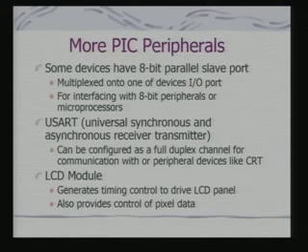There are other PIC peripherals besides what we have discussed so far. One is the 8-bit parallel slave port. If you look at your digital I/O pins or the ports that we have discussed, what is the difference? We have considered and used them as single bit I/O ports. I can set individual bits to be either in input or output mode separately, and I can read them.